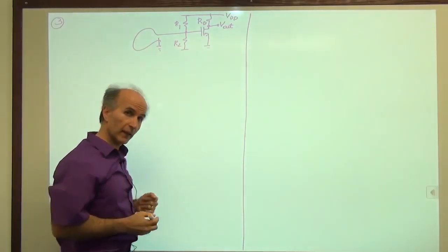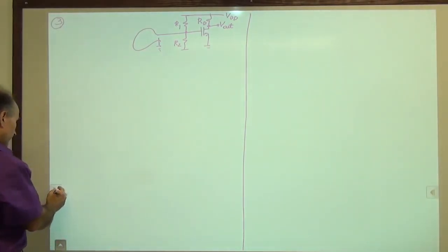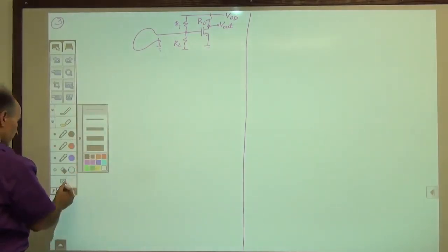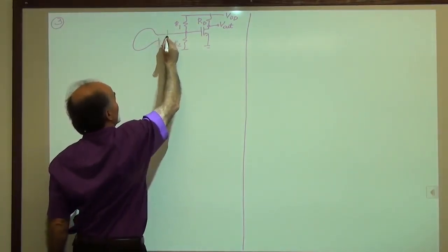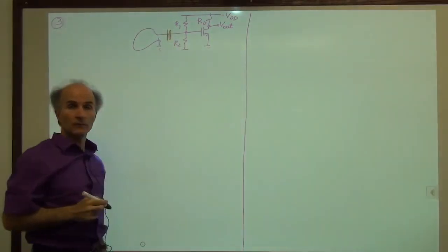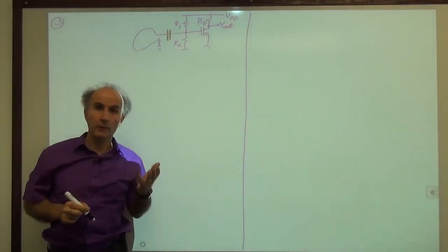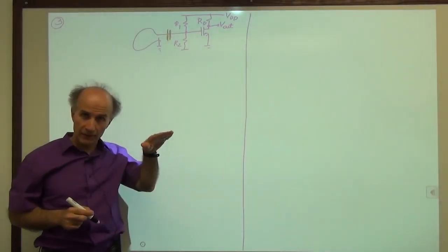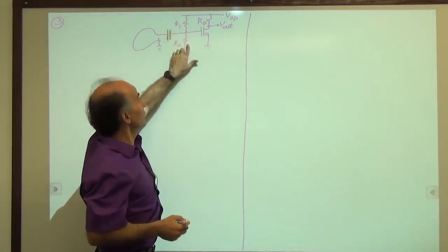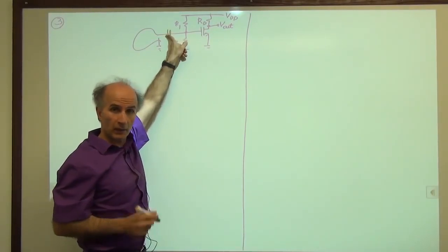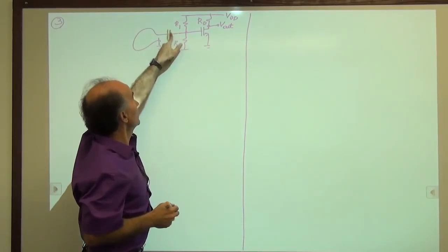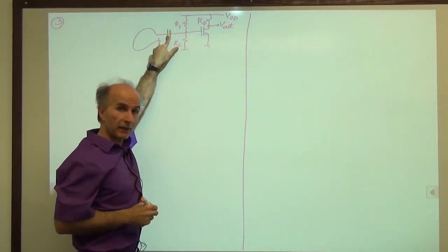Well, the simplest solution in that case would be to add a capacitor here to isolate the DC levels from each other. So we would add a capacitor right here. So now we know that a capacitor is an open circuit as far as DC levels are concerned. So as far as biasing is concerned, we have V0 because R1 and R2 are generating that. There's no DC current this way, so we're good. And this antenna doesn't bother this node because this capacitor blocks the DC connection.